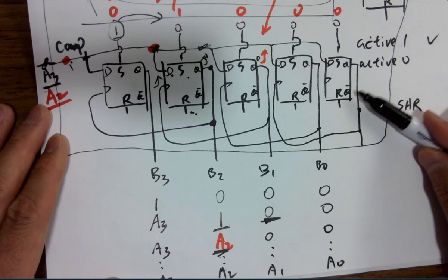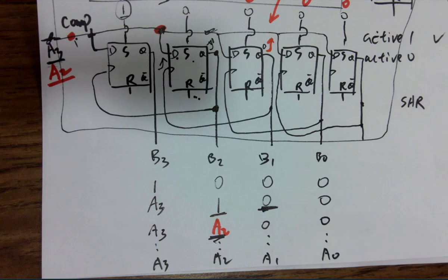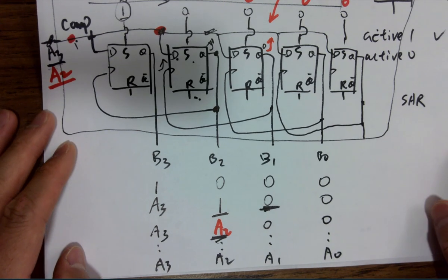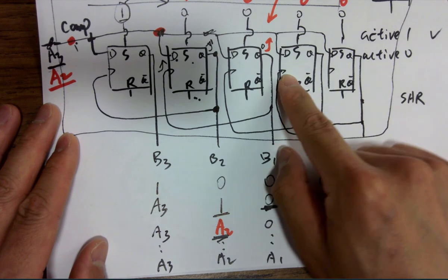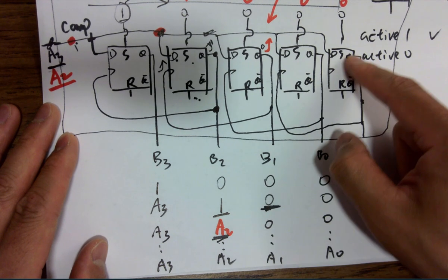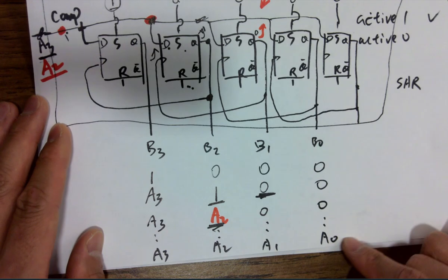Let's do the n plus 1. What is it needing? Additional. Will that tell you when it's done? Yeah, it's holding that value and eventually provides a rising edge, because we need a clock, right? Whenever the 1 is being shifted to here, it provides a rising edge to register A0 to here.